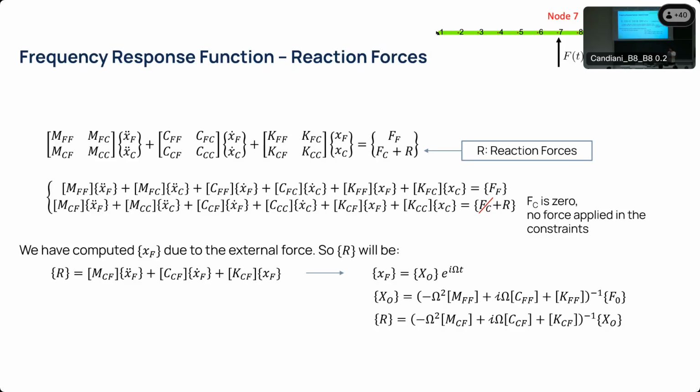So we could discard them and we could get a matrix relating the input force, which was, again, our input, so a known quantity, a thing that we use to find the frequency response function, and so on and so forth. In any case, a quantity that we use to find the value of XF. So we can assume that at the end of all the things we did before, we know, for each of the input forces, the displacement of all the free nodes.